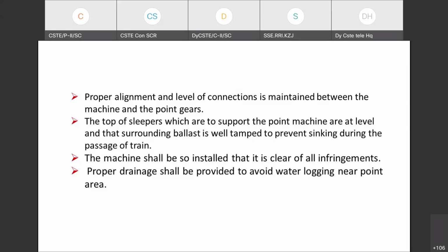Whether it is a goods train or a coaching train, we should ensure this whenever some maintenance or adjustment is required. Now there is again a checklist for the ESM: what are the occasions for which we should take disconnection, and the occasions for which disconnection is not required. That should be meticulously followed. Otherwise, it can lead to an unsafe situation.